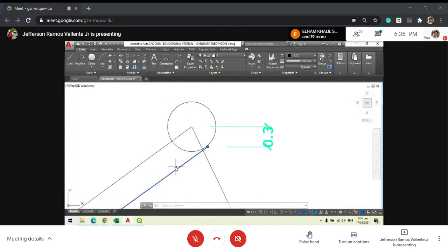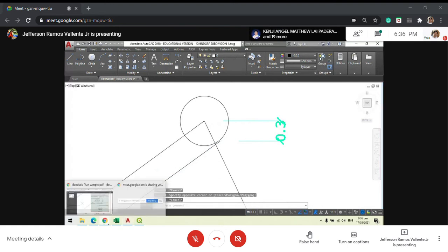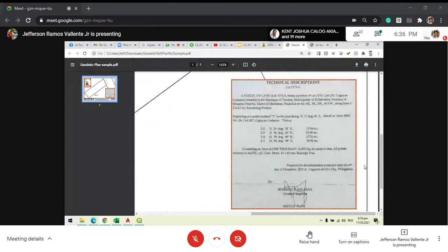But keep in mind that in the actual survey of the lot, it doesn't close. Okay? The purpose of having the lot description is for legality purposes. Okay, in cases of lot dispute, the basis in court is what is indicated in the land title. Okay? So only the land title will be used. And embedded in the lot title are errors. So that's part of your knowledge as a soon-to-be civil engineer. And the purpose of having those errors is to be integrated in the area calculation.